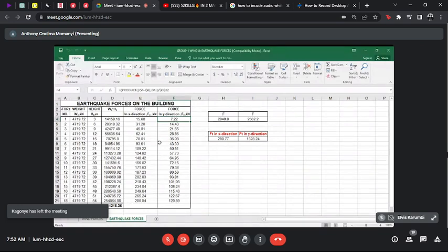Okay. So then the check that you do to confirm that your calculation is right: you see your column E, you can do a sum at the bottom of total forces for all these floors, and that total force has got to match the value on your cell H4.